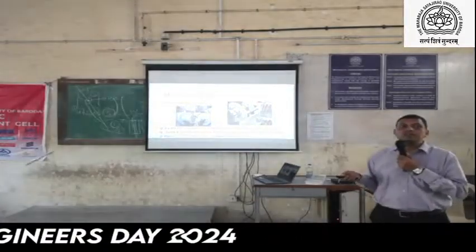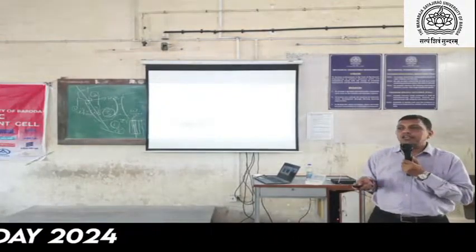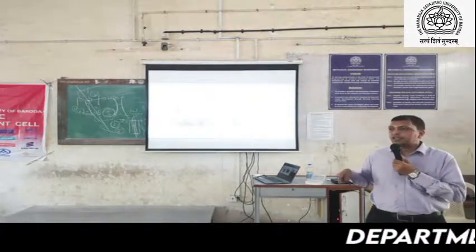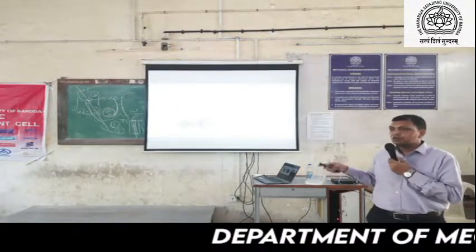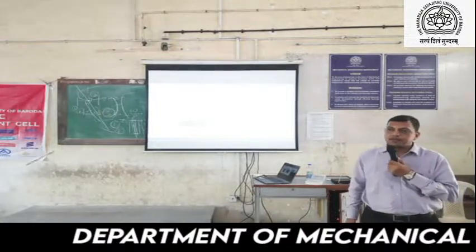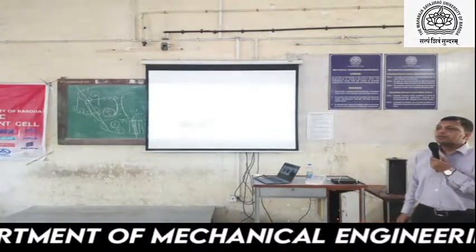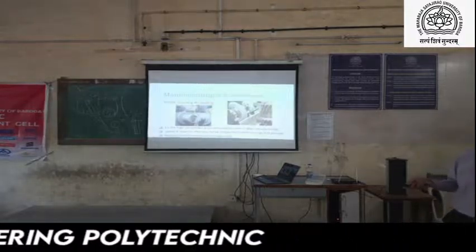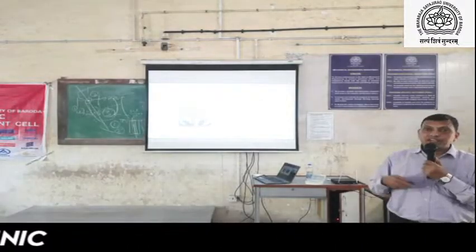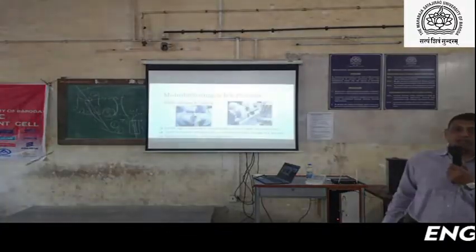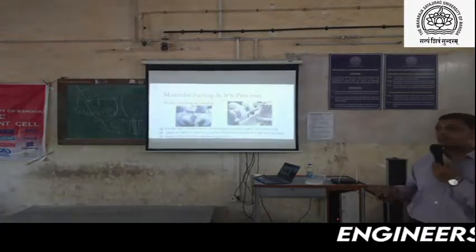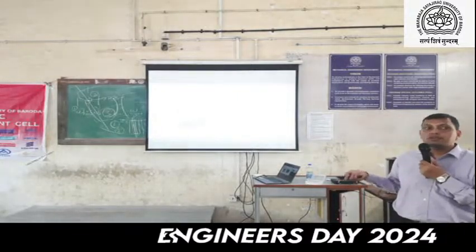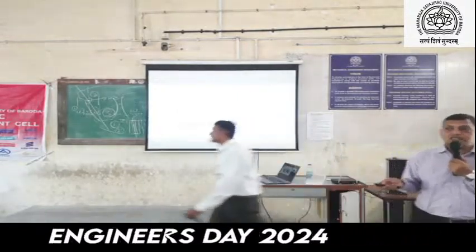In the grinding operation, there are different accuracy classes, defined by the accuracy of the pinions or the wheel. In low speed applications, we normally consider class 6 to 7 as per the standard. Whenever we go for high speed applications, like turbine, gearbox and bearing, we require a higher accuracy class. In that case, we have to go for class 4 accuracy.